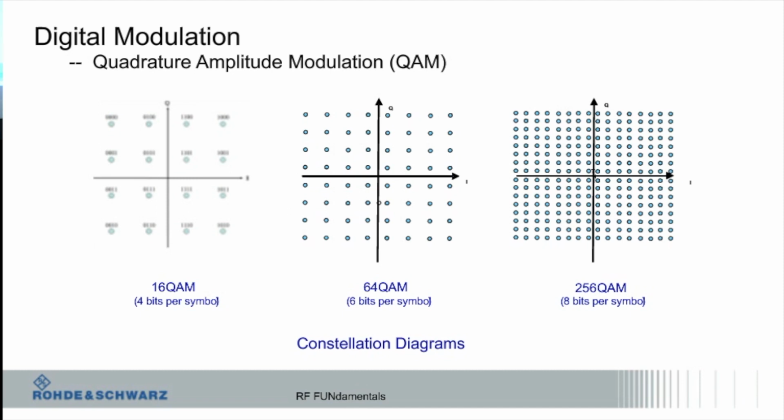Question? Before talking about encoding, yeah. What's the relationship between data rate and carrier? So how much faster does your carrier need to be than the data rate without doing any encoding? I mean, the carrier really has nothing to do per se with that. The carrier is basically the signal that I'm going to transmit the information through free space with. Obviously it's higher, but typically it's orders of magnitude higher. So is there anything fundamentally limiting me from putting a gigahertz data rate on a 10 gigahertz signal? Does it affect SNR or anything like that?